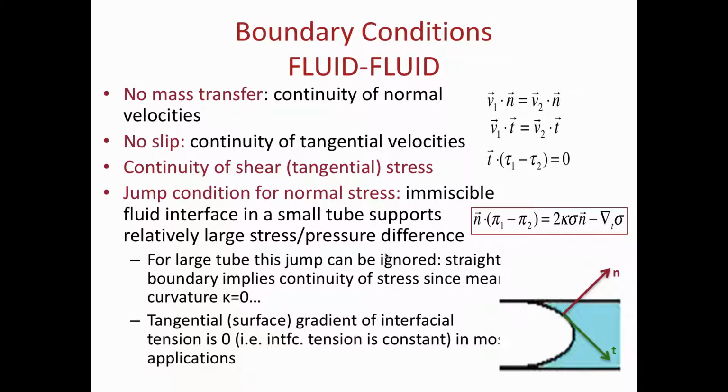So the interesting consequence is when you're pushing through a tube, the same way you push in is the same way you come out. But if you're in a more complex porous medium, which we always are, then the way you move in and the way back are different. The interface will curve in response to the required pressure. You are changing pressure from the outside, either increasing pressure moving in or decreasing pressure moving out, when you're draining or imbibing.